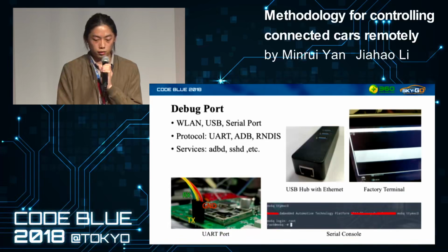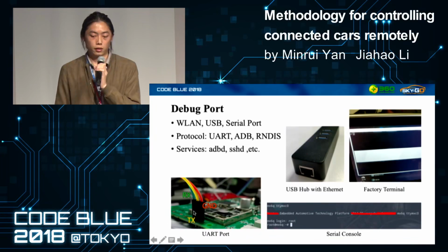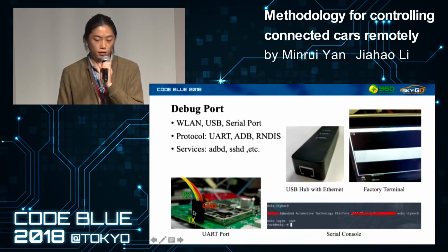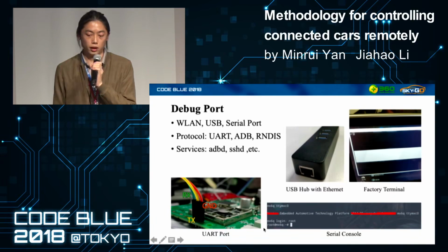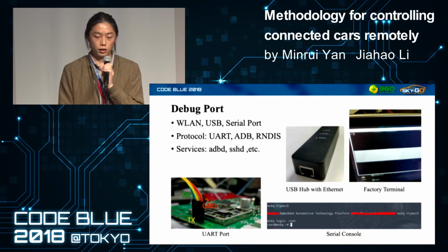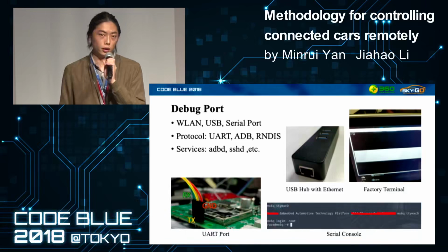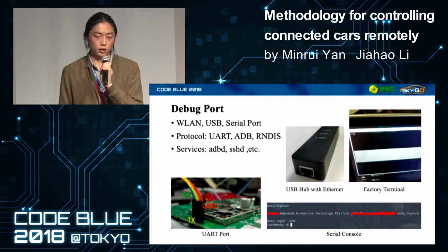On the PCB board, like this, there is perhaps a UART port on the side of the SoC. A TTY console runs on this port. You can use a USB serial adapter to access the debug shell.